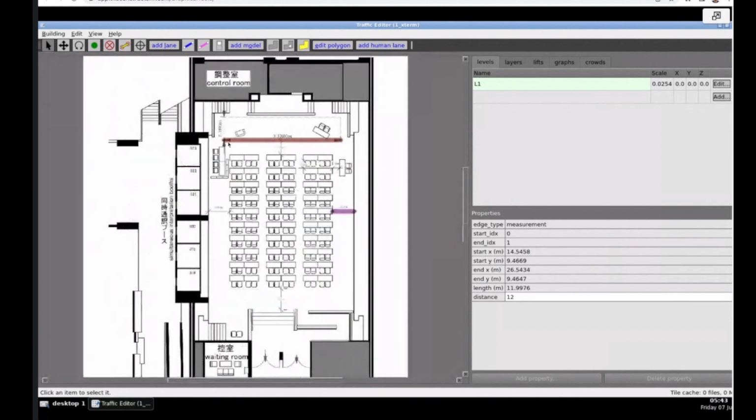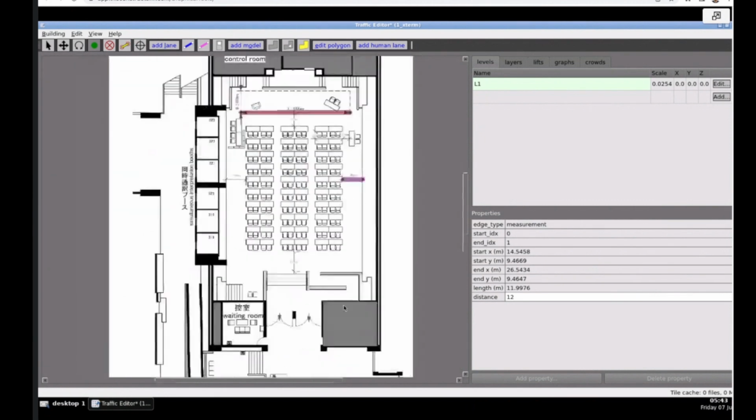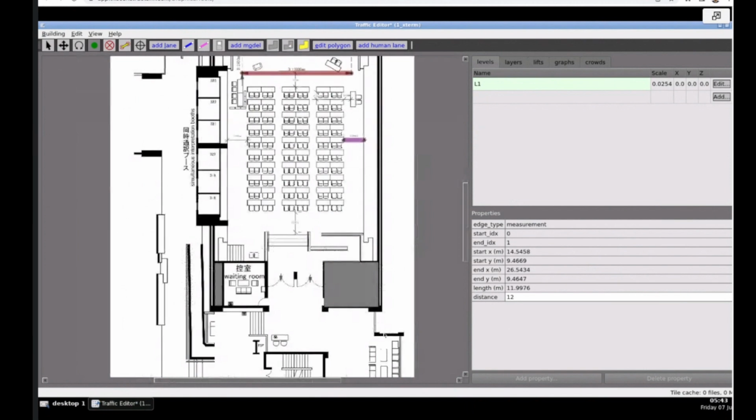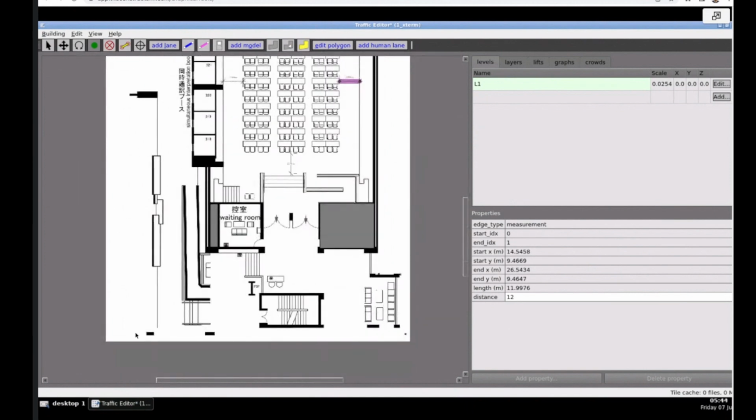This is a pretty large room, and I'm just going to arbitrarily define a bounding area for the floor. In order to do that, we need to create certain vertices, which will define the boundary of our floor. To do this, you should see this green circle icon here that says Add Vertex. The short key is V. So I'm going to create a vertex over here, maybe another one all the way out here. Again, you can do this however you'd like. I'm just arbitrarily bounding all the 2D space that I see here.